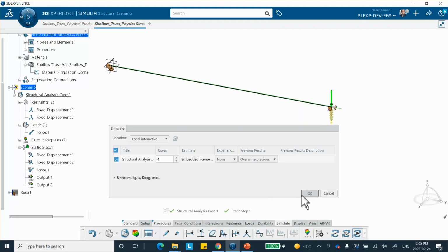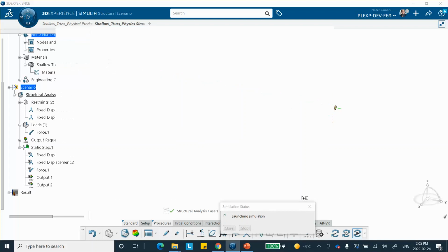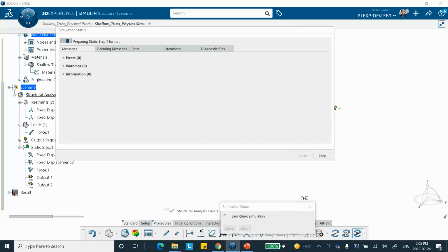You will see that it'll give me a displacement of 55 millimeter, which is fine. It shows you that it's correct. However, it will not let me plot that force displacement curve because I did not ask for the proper data to be able to plot that.